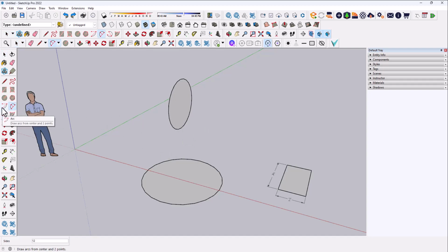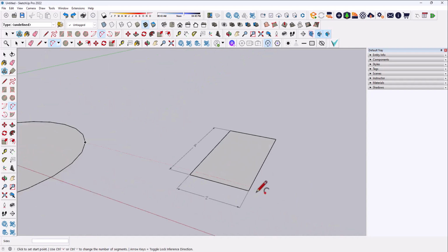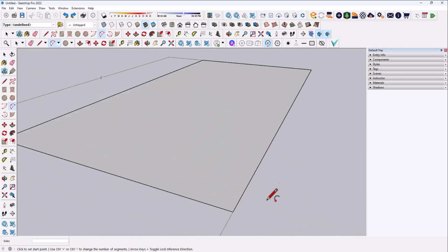So there are other 2D commands. Arcs, there's a couple different ways to make an arc. Let's say I wanted to create a filleted edge for this edge so that it has a rounded rectangle. There isn't an easy way to do that, but the workaround in SketchUp is to create a 2-point arc. Click on one edge, wait until this snaps purple and you know it's tangent, and then you can set the radius. Let's say we want this radius, let's just say 2 feet, enter.